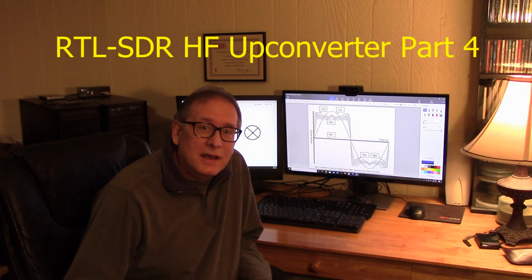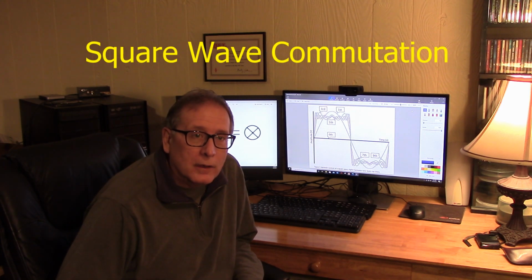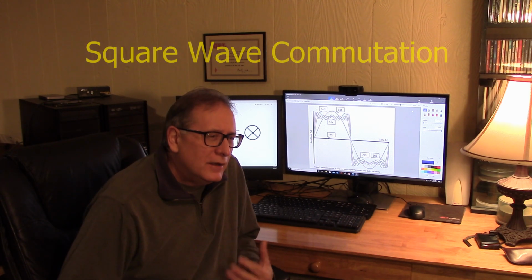Is everybody bored yet? This is part 4 of the RTL SDR video series, and I would really like to try a square wave to drive the local oscillator port of the mixer. This kind of seems awkwardly reverse since we've taken great pains to filter the sine wave and to try to reduce harmonic content before introducing it to the mixer. Now we're going to put this square wave in there.